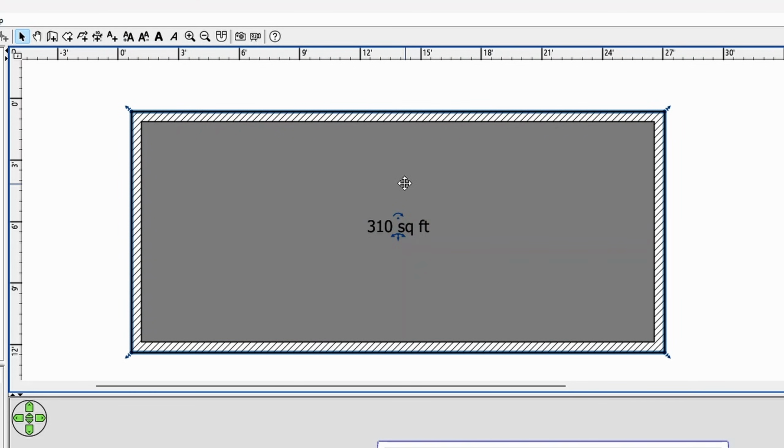It's good to know that this automatic room tool works with any fully enclosed wall space, not just rectangles. If a room cannot be created, check for small gaps between the walls. Besides automatic creation, you can also draw floors manually. This method is useful when you want to start with a foundation or a custom surface.